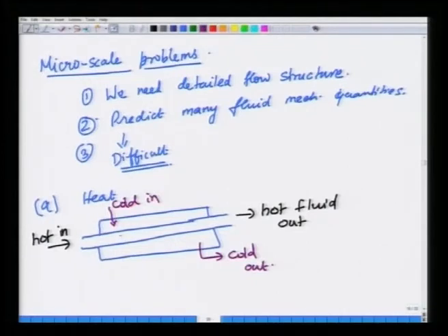So, you want to cool down a liquid stream in a chemical process industry, you will use heat exchangers. So, this is a very simple example of a heat exchanger. Simply have two streams which do not physically mix with each other, but they can interact with each other through the walls of the pipe, thereby exchanging heat.